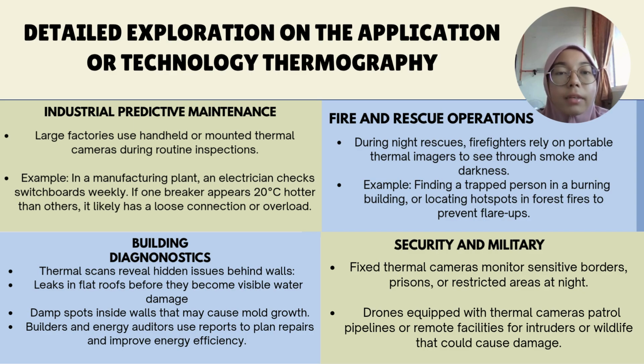So, in this slide, we will explore in detail the applications of thermography technology. Just like I told you earlier, there are many major fields that use thermography in their instrumentation concept. The first one is industrial predictive maintenance. Large factories use handheld or mounted thermal cameras during routine inspection. For example, in a manufacturing plant, an electrician checks the switchboard weekly. If one breaker appears 20 degrees Celsius hotter than the others, it likely has a loose connection or overload.